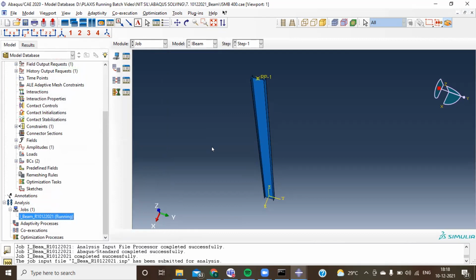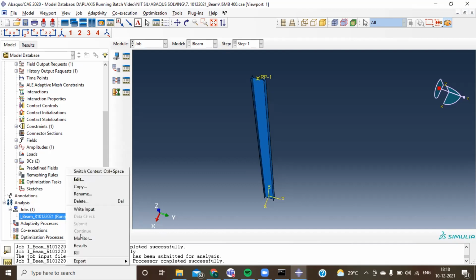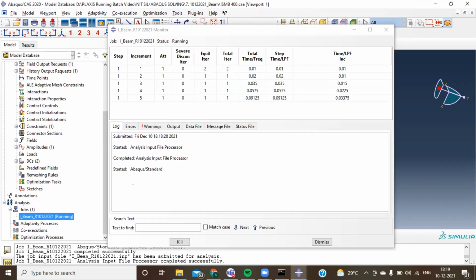F equal to kx, right? So when I'm getting an error solving for the force, I will feed the displacement and solve for the force. Vice versa, I can calculate that. So when I'm facing errors with the force, I'm trying to apply the displacement now. That's it. Even in your problem, you can try to apply the displacements and eliminate the forces, then it should solve automatically. Okay, sir.